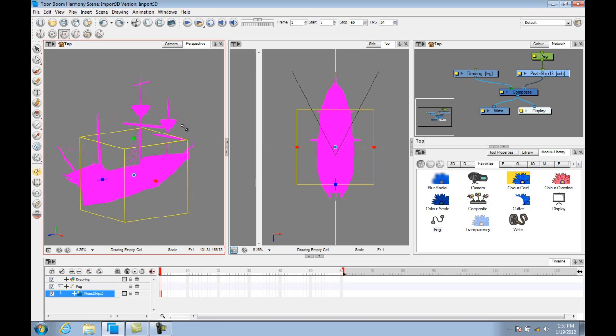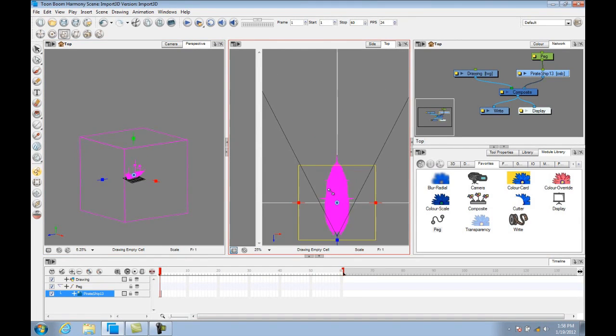Now you can see that this is a cube, and that if you want to scale in any one direction, you can select one of these points on either of the faces to scale disproportionately. So if I want to scale this way, so that's either a stretch or a squash, I would select that green square. However, if I'd like to scale proportionally, I can grab one of the corners and hold down Shift and then actually scale proportionally. And let's do that now and make our ship more in proportion to what it should be for animation. So here we can see it's quite a bit smaller now. I can zoom in using the number 2. I can go back to the Translate tool and drag it into view.